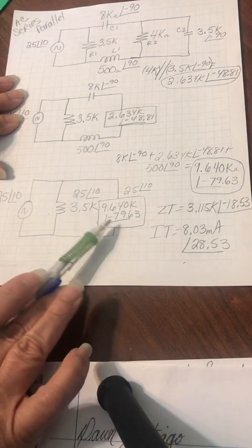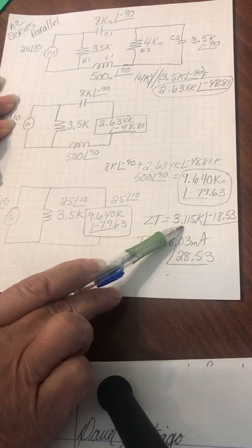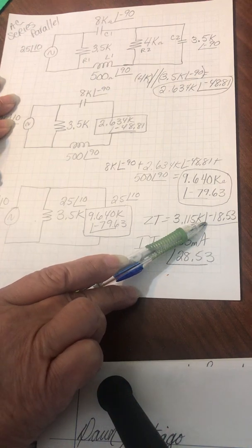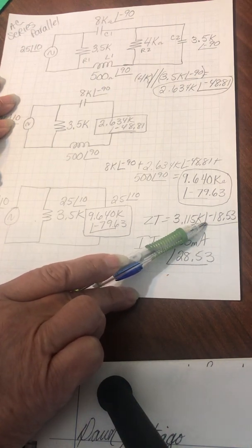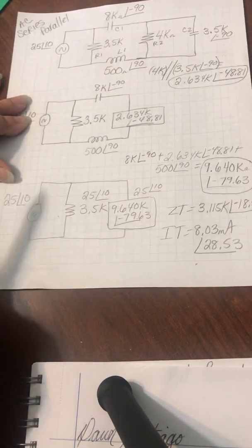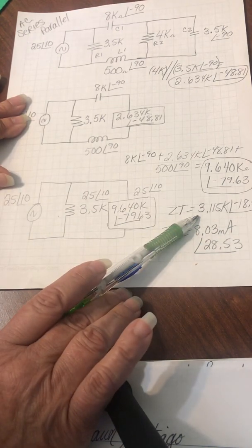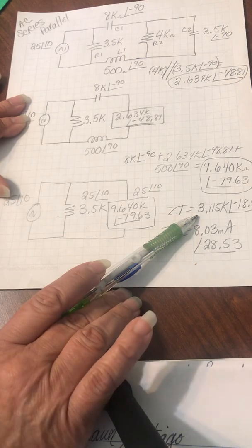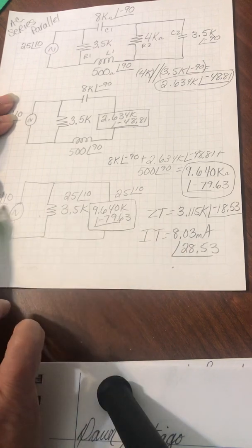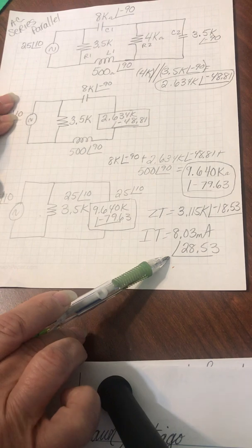When we do that parallel combination, your Z total is 3.115 k ohms at an angle of -18.53. Now we can get I total. I total is just E total, which is 25 at 10, divided by your Z total of 3.115 k ohms at -18.53. When you do that, your I total is 8.03 milliamps at an angle of